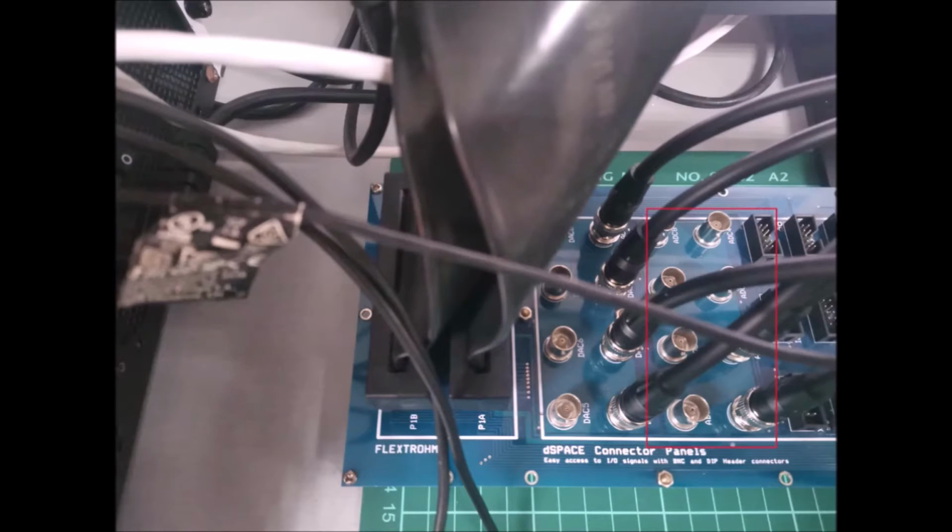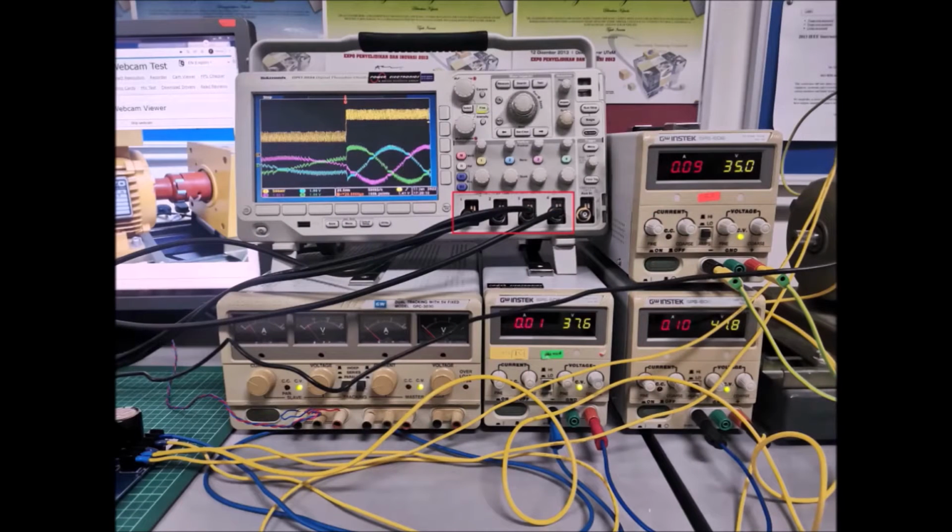The ADC consists of 8 channels and also another 8 channels for DAC. ADC is used to convert analog signal to digital since the current measured from the current sensor is analog. We use 2 ADC channels and 4 DAC channels. The DAC channel is connected to the oscilloscope in order to observe the output.